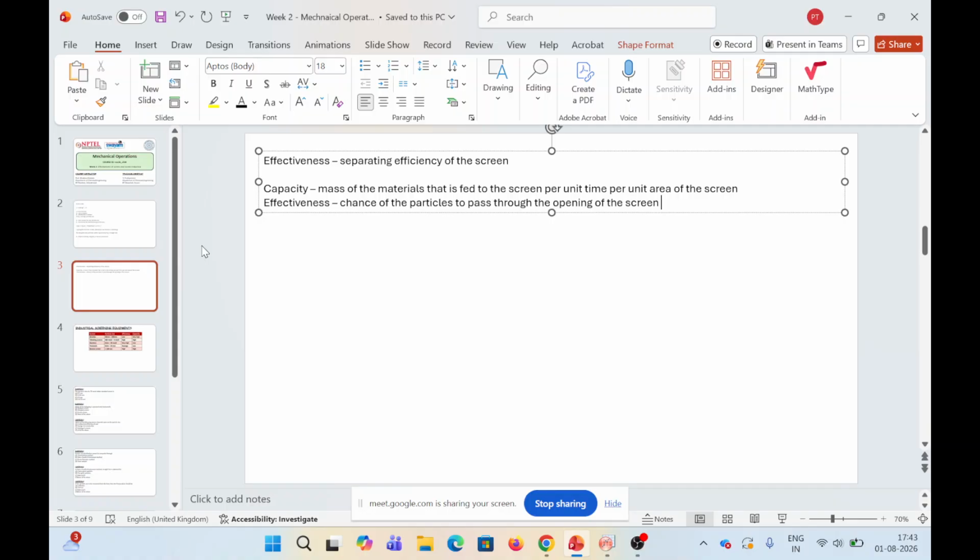When we do this sieve analysis, we need to repeat the analysis three to four times, and also move these screens or provide some sort of motion to them, so that you give the particle a chance to change its direction or configuration so that it can actually pass through the opening.